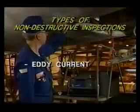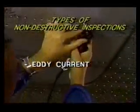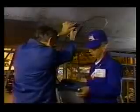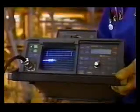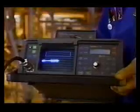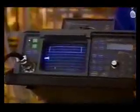Low-frequency eddy current inspection can be used to detect thinning in multi-layered structures due to corrosion and cracks. The inspection is performed by inducing eddy currents into a part and electronically observing variations in the induced field. The character of observed field change is interpreted to determine the nature of the defective condition. Eddy current is a good means for inspection because the inspection can be performed quickly with standard equipment and will obtain a high degree of sensitivity and reliability.